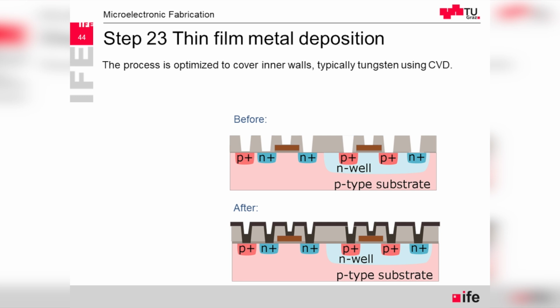Second property is that when we then put another metal which will have a good conductivity, typically it's aluminum, this aluminum also needs to attach well to the surface so that we don't have some voids. The filling is very uniform and proper everywhere. So this good attachment is another reason why we use this lining. The lining is done with chemical vapor deposition, a thin film, slow process, but it's worth it.